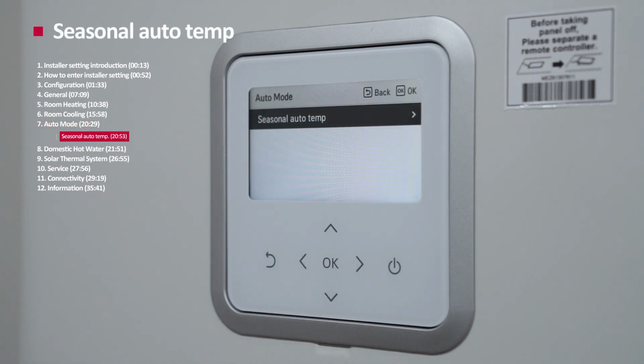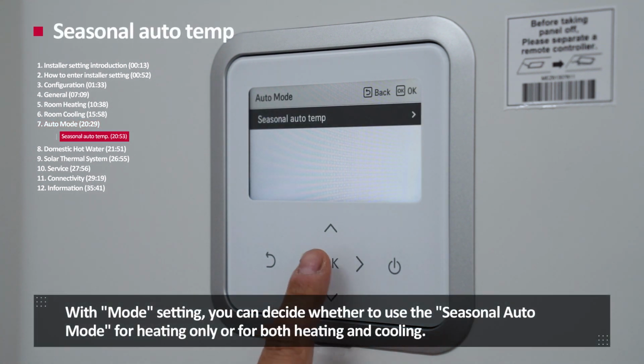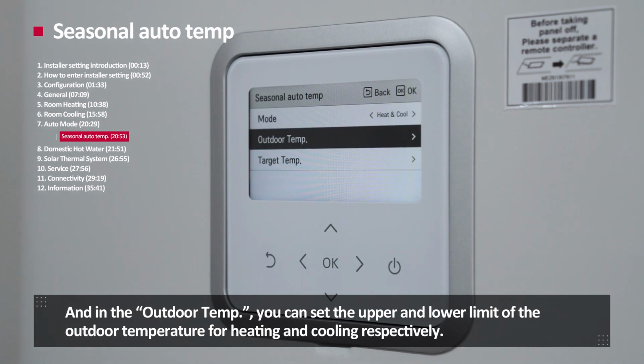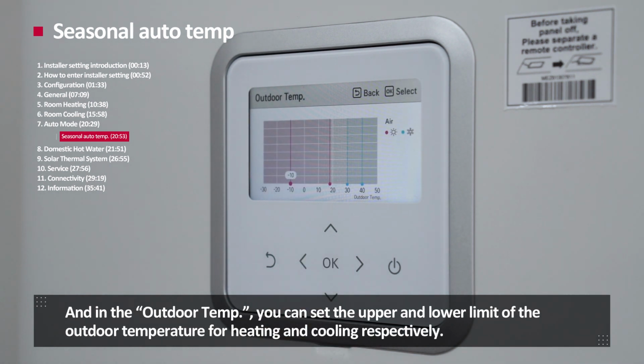Seasonal auto temperature. With mode setting, you can decide whether to use seasonal auto mode for heating only or for both heating and cooling. And in the outdoor temperature, you can set the upper and lower limit of the outdoor temperature for heating and cooling respectively.